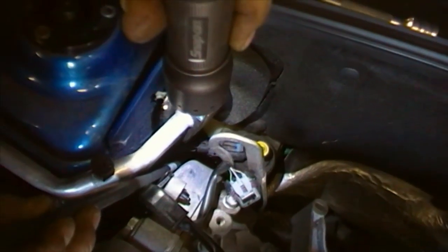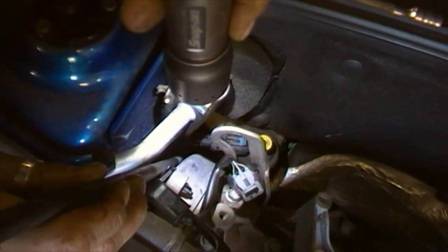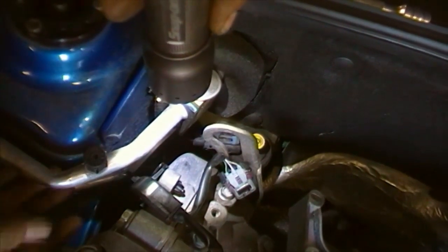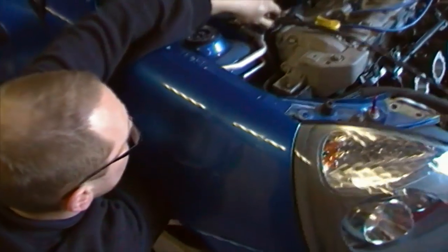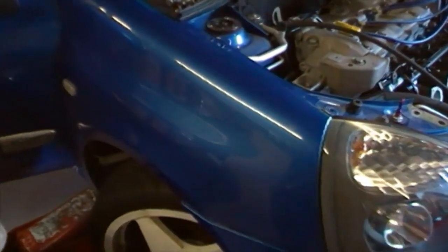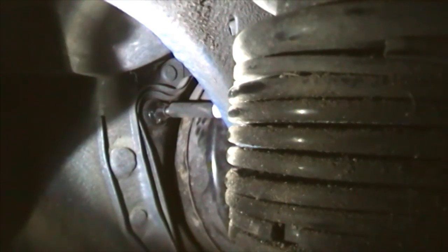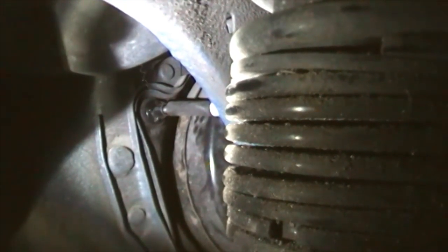Now put the outer throttle cable down behind the heat shield just underneath the brake reservoir here, and then I'll need to go through the inner arch to find the cable. Here now that we've got the outer throttle body cable inside the grommet and the cable holder.